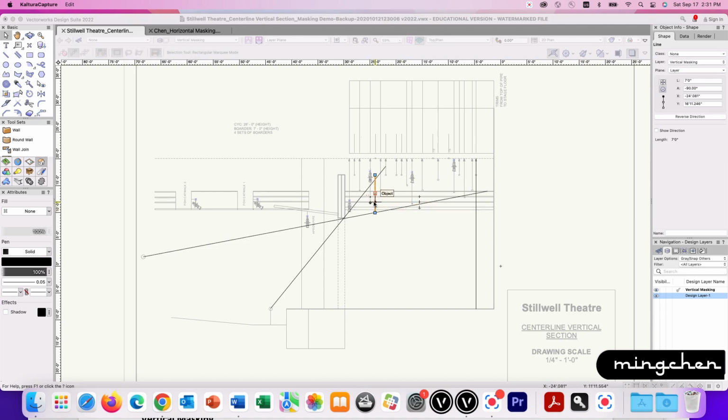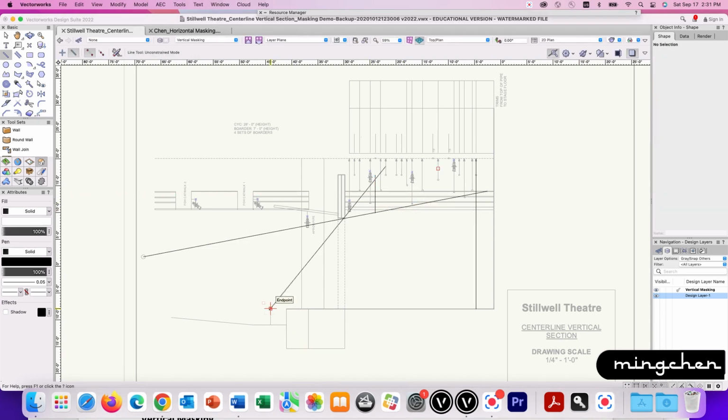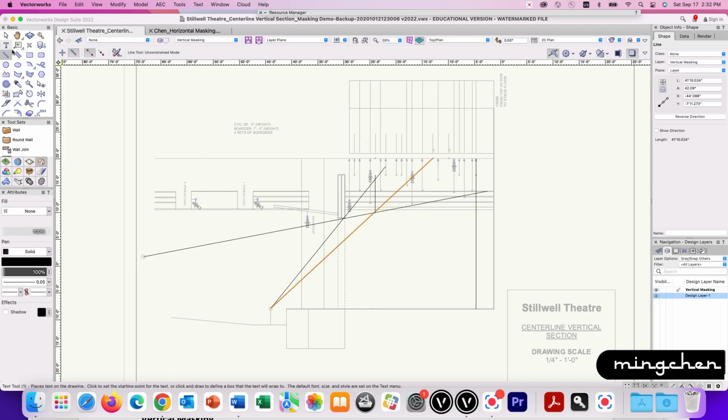Draw a second side line, starting from the critical seats located on the first row of the house. Run the line through the onstage side of the first border all the way to the offstage space and make the second click. This is the second referential side line. Draw a 7 feet high vertical line. This is your second border. Align the border with one of the batten positions.